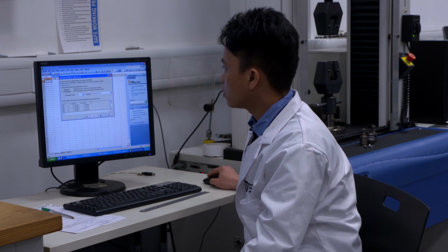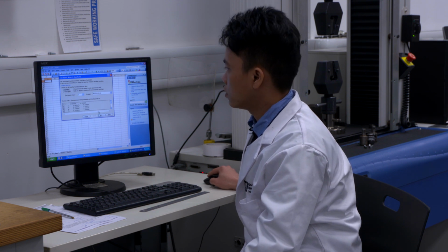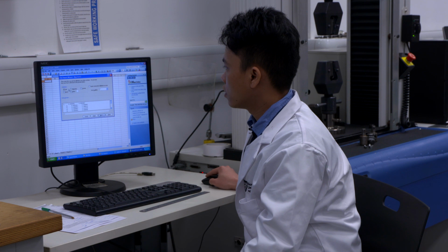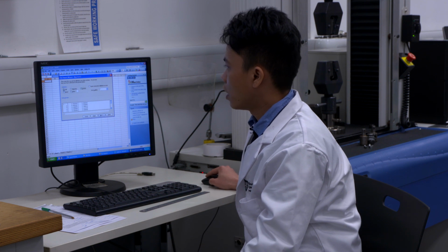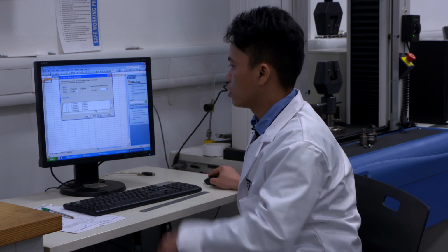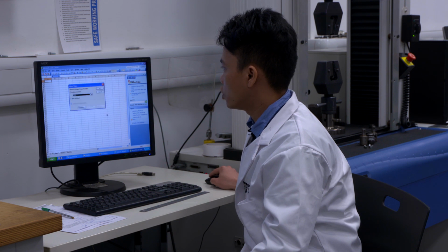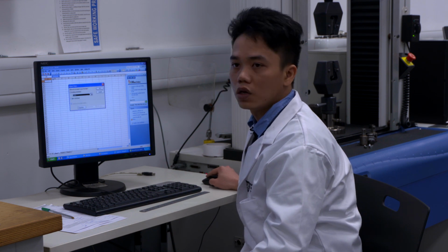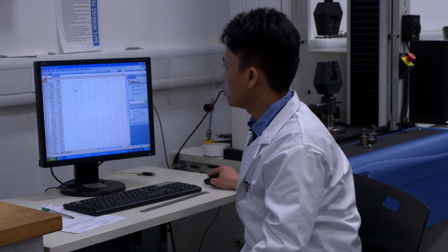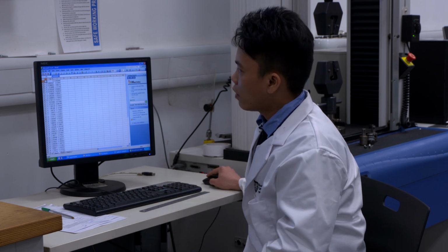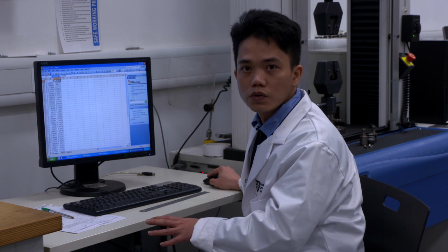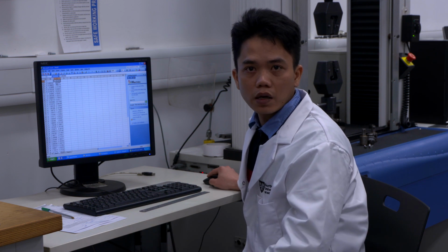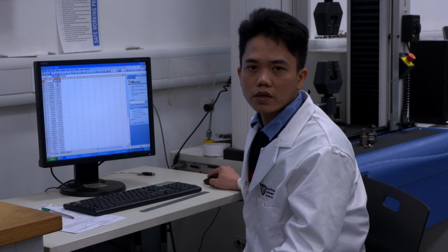Click on it, and then use delimited, and then next, comma and tab. Click on tab and comma, and then click on finish. Choose the initial position, and then we have a single column ready for you to calculate the stress and strain.